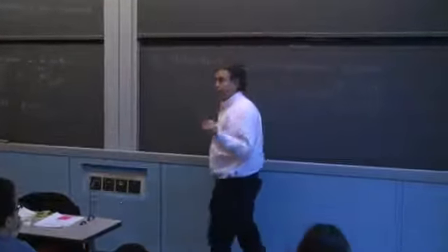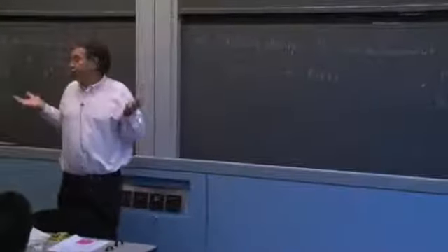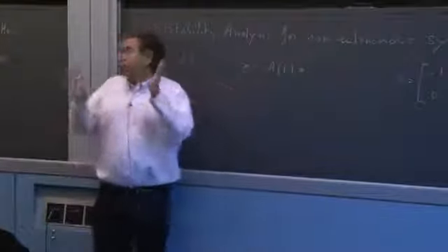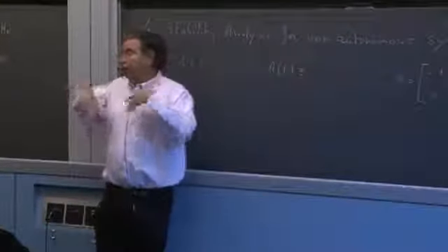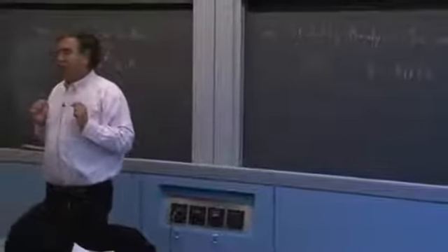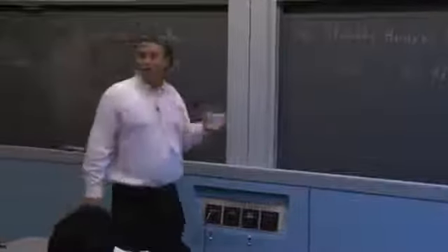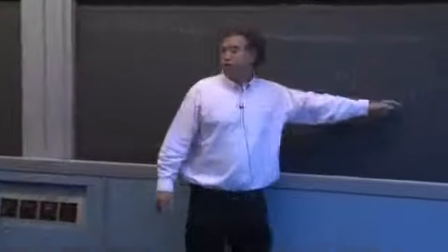It will go back to 0. That would be a natural first conjecture. How do I analyze the stability of this? Well, I look at every t, and if at every t the eigenvalues are in the left half plane, the system will tend to 0. That's a conjecture. Now, it's not always easy to prove conjectures, but sometimes much easier to disprove them. So this system shows that this conjecture is not true.